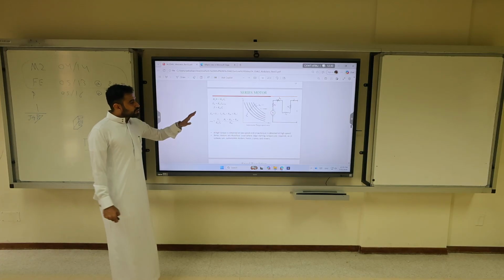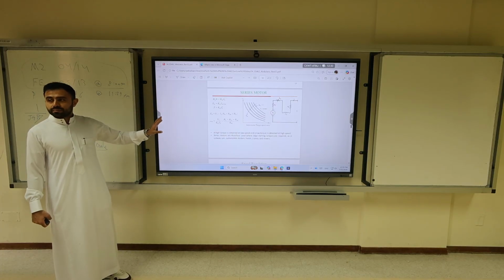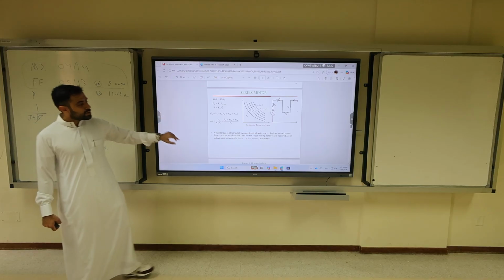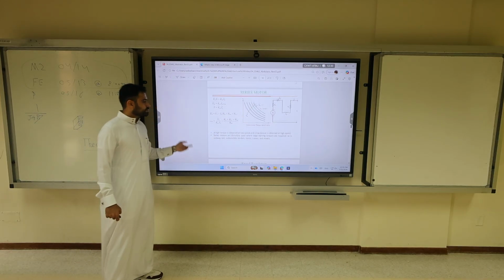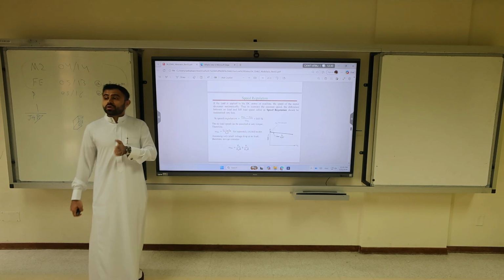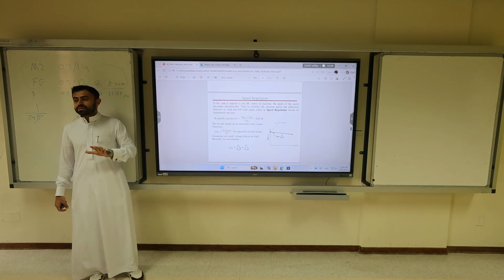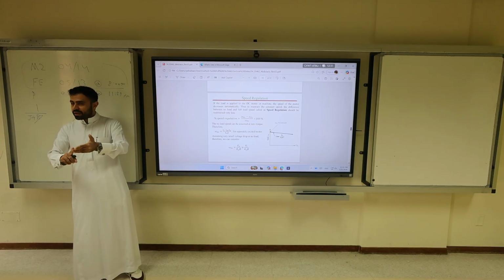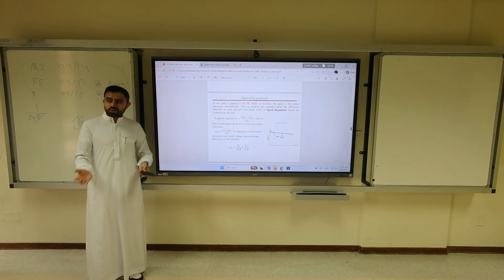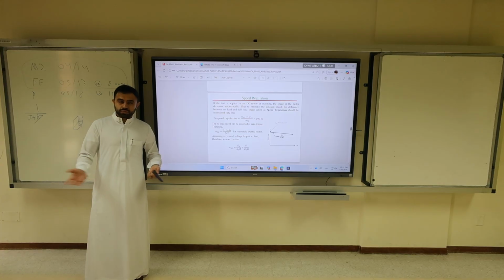So any question about the series motor control? So how to control it? Using these curves of series resistances. We're talking about non-power electronics. No choppers, no VSI, variable drives. This is just pure resistance, voltage, and field control. Is this used nowadays? No.